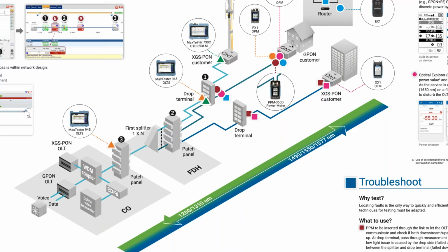Now, of course, this is all going to be during the construction phase when we don't have any light on the fiber. Now, if you want to do this same type of testing during the deployment or after you have the OLT connected and you have light on it, then you're going to need some more specialized equipment, and that's going to be something in the realm of a live filtered port with a wavelength that's not going to be on the network that you're using.